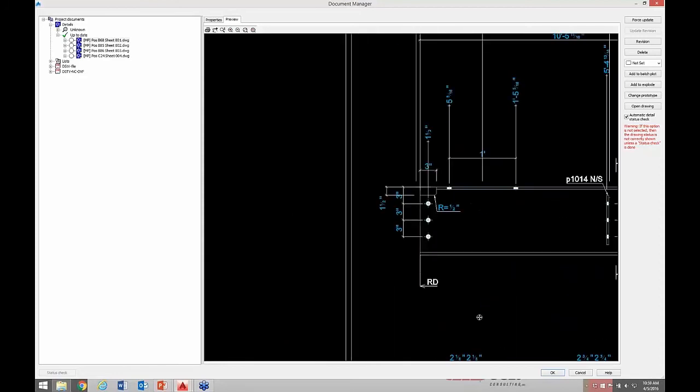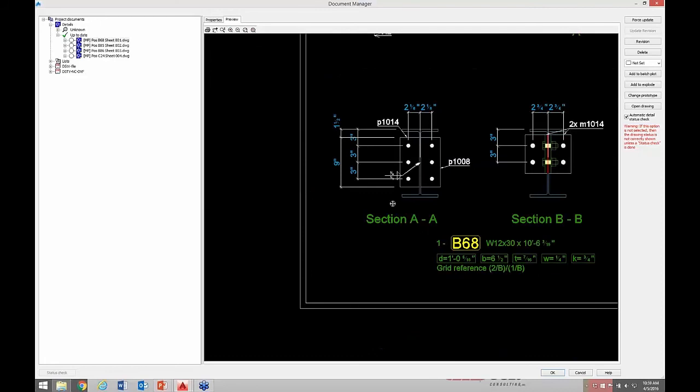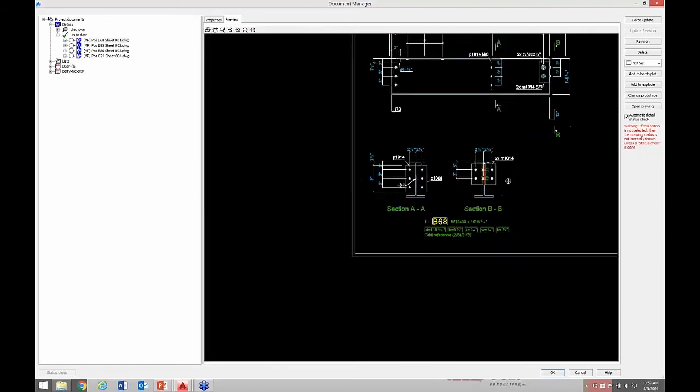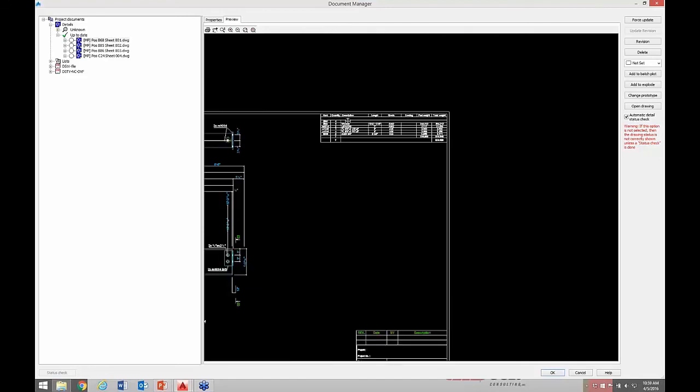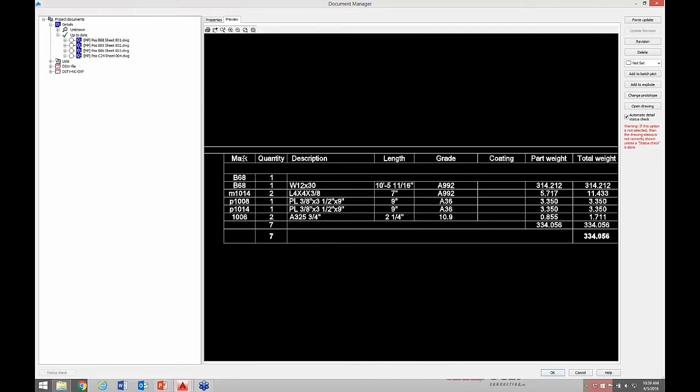Bolt holes, cutbacks, whether we need a reference dimension, automatic section cut creation from the element, and we see those generated here in our two sections, showing the clip angles, and the all-important bill of material at the top here for this assembly. Okay, and the mark association with that and what parts and pieces there are. And I can review each of these.